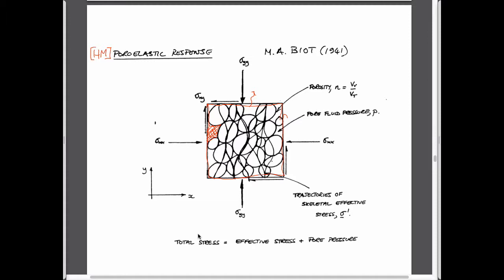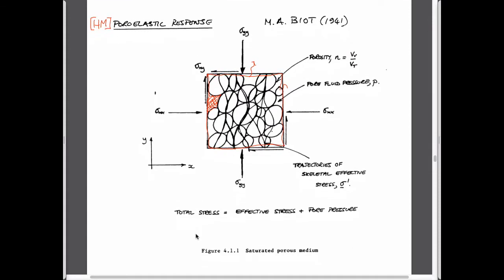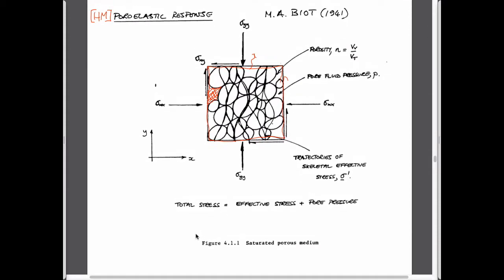And so we haven't talked very much about effective stresses and total stresses in this class, but the essential component in understanding this pore mechanics is to understand that there is a concept which is effective stress, which says that the total stress that you apply to this system is equal to, in the geological and geophysics literature, the sign convention is always written in this way. It's equal to an intergranular stress plus the fluid pore pressures.